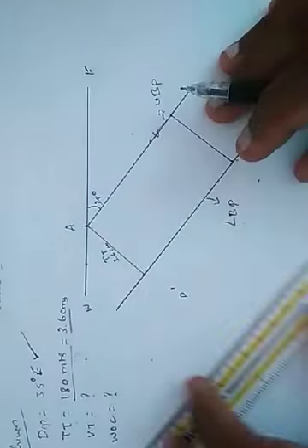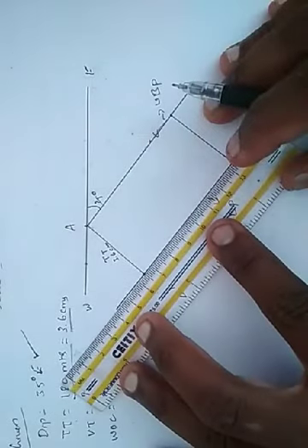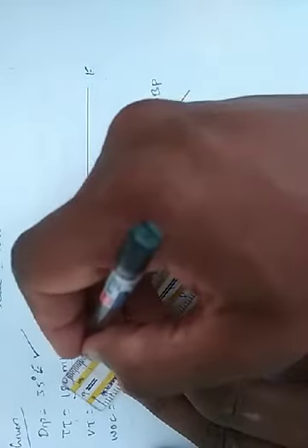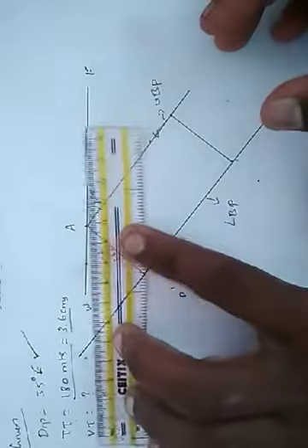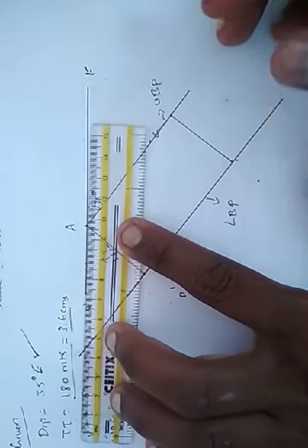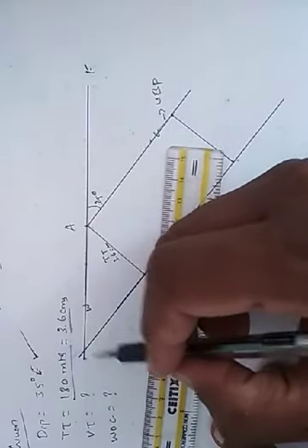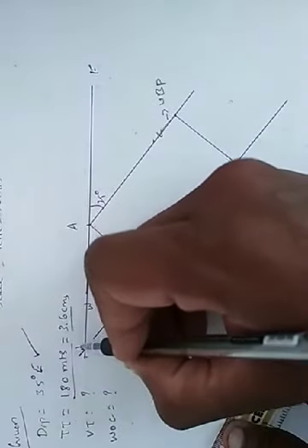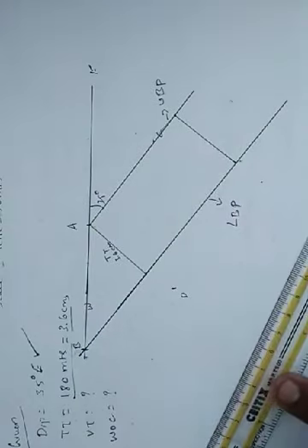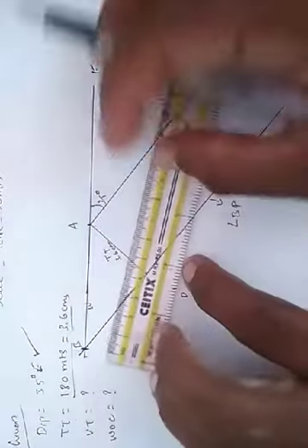So I will extend this line upwards, and I will draw the surface line that should intersect with this lower bedding plane. Now this point is marked as B. Now we need to measure the width of outcrop where we got the 2 bedding planes here.